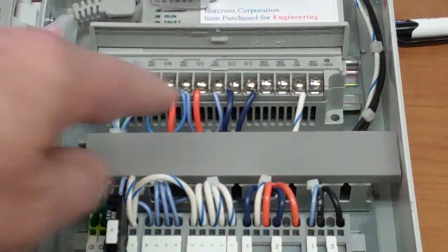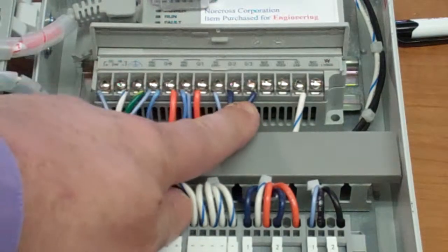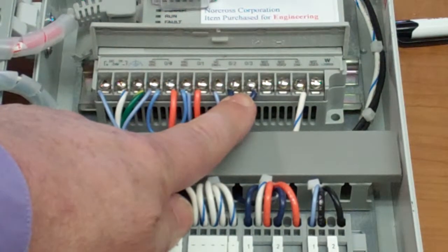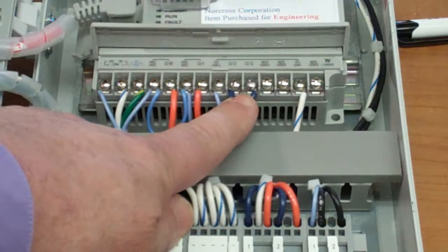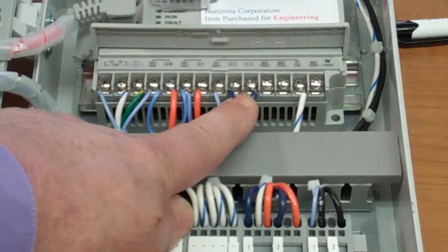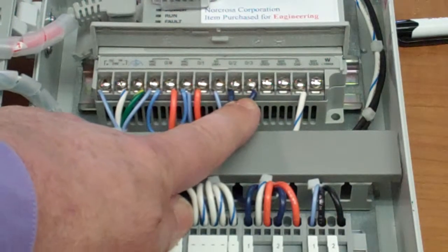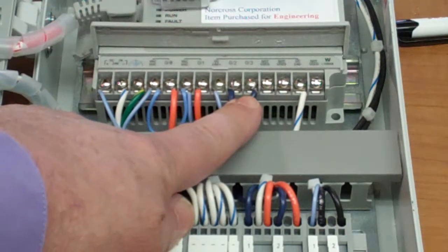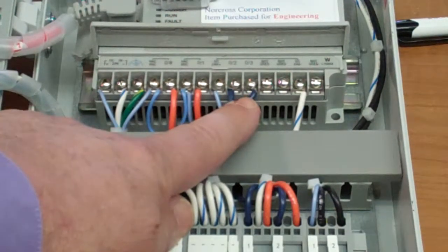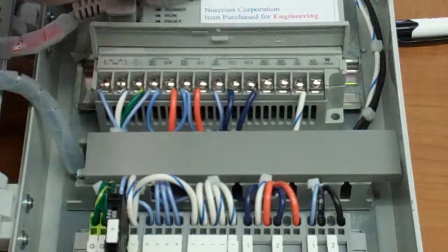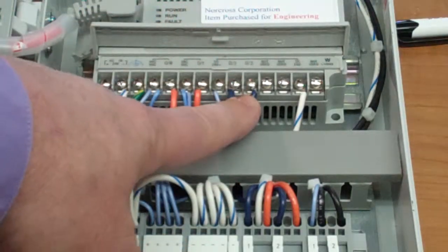So FET outputs are transistor outputs. Transistor outputs are solid state junctions. They're not mechanical relays. They're solid state. They can age, they can wear out, they can be overloaded, they can be burned. In industrial process control, you don't want to use a FET output unless you're driving another transistor. Having a FET output drive a regular valve, 10-watt valve, is a mistake. So we have isolation capacity on this.